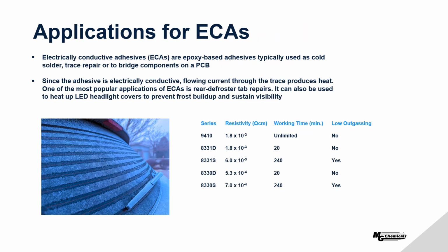Finally, we have our electrically conductive adhesives, or ECAs. These are epoxy-based materials used for cold solder or PCB trace repair. Much like rear window defroster tabs, ECAs can be used to fabricate heat grids over headlight surfaces. Our customers use ECAs for LED headlights or on snowplows to sustain visibility during operations.